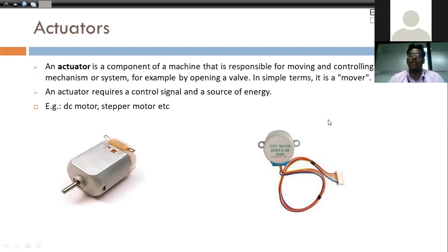If you want to drive any motor, you need a driver IC. The driver IC is the main thing to drive the motor. Whatever signal you pass, you need to write a condition for it to rotate clockwise. You can't switch from positive to negative and negative to positive manually to rotate clockwise and anti-clockwise, so we use drivers to control actuators.